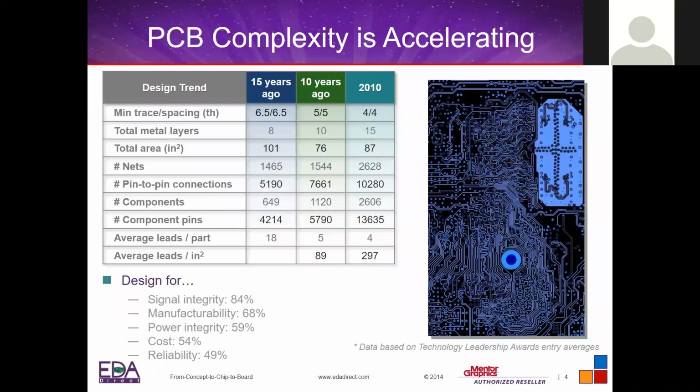So in terms of PCB complexity, we see that it is increasing over time. Basically, the form factor has been reduced to smaller and smaller sizes, with the exception of some products, of course. But then the number of layers might be increasing, the stages are getting smaller, the clock speeds and switching rates are getting higher and higher. So therefore, it becomes complicated nowadays. You may have things like PCI Express Gen 3, which is 8 gigabit, Gen 4, which is 16.